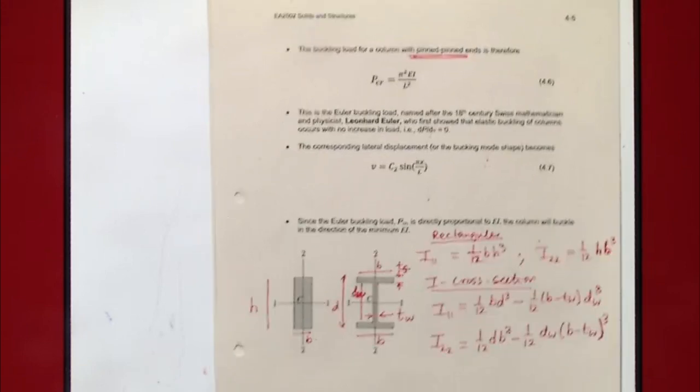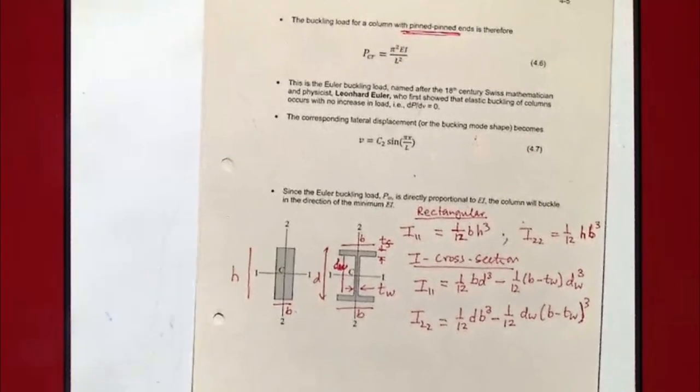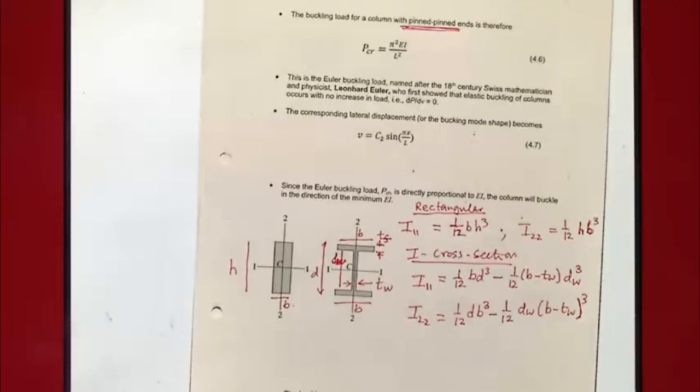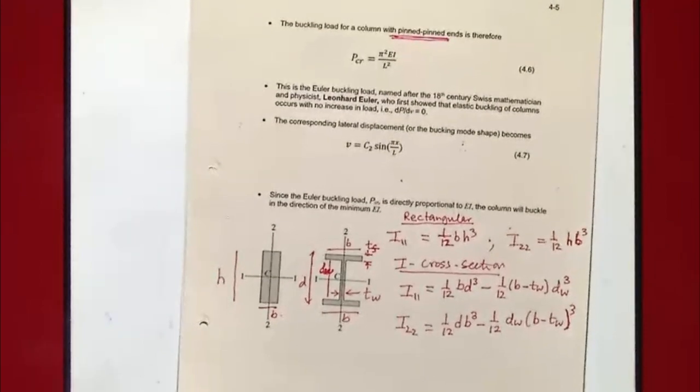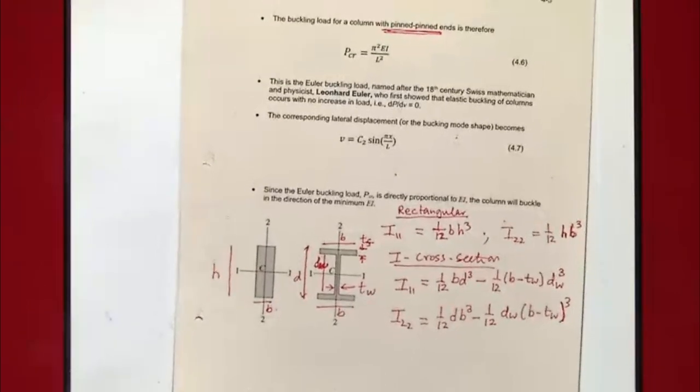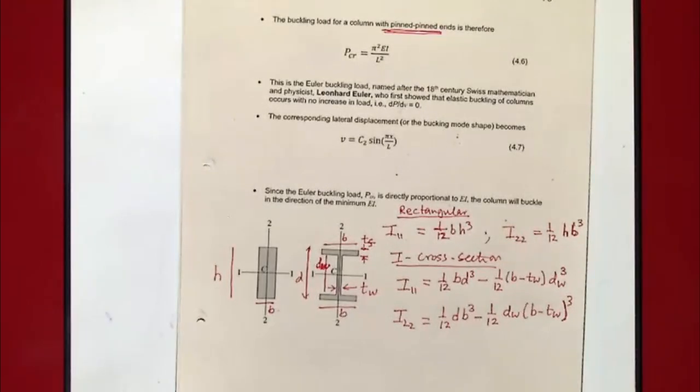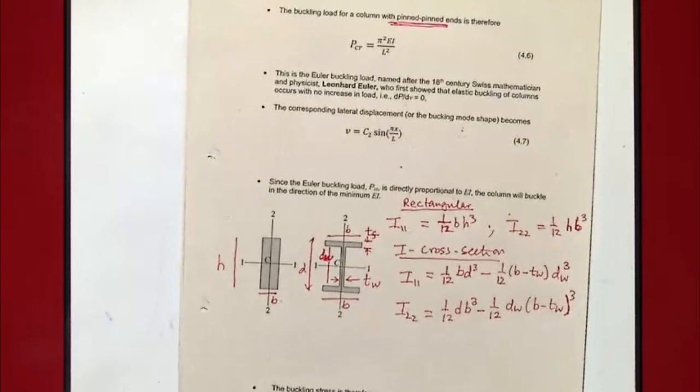So we have to calculate the buckling for different moments? Yeah. So if you have any cross section that is not a square, you have to determine what the buckling mode is along the two major axes for that particular cross section. Can we do an example of that? Sorry? Can we make an example, please? Yeah, you will see when we get there. Okay, so let's finish all the theories first.